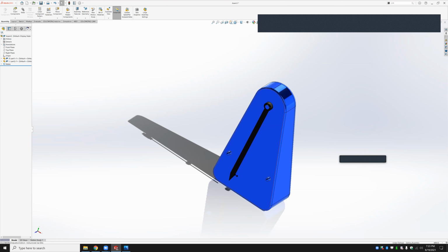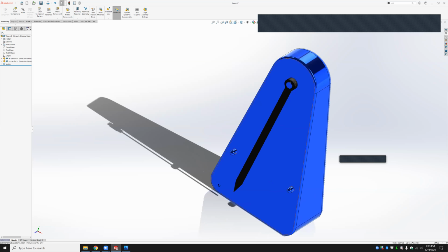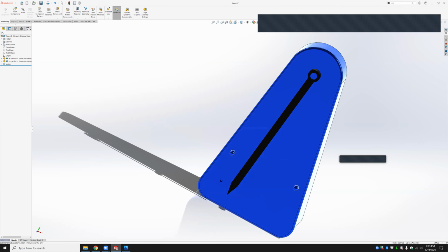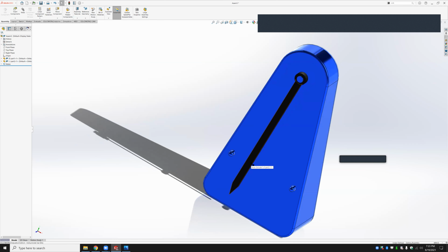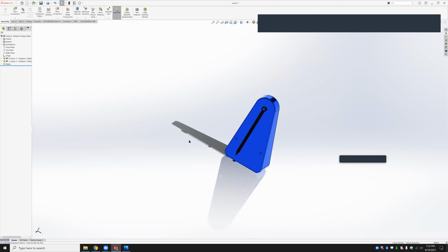Okay. So because I haven't introduced the mate yet, I'll introduce the limit angle mate. It's an advanced mate, and I think it's worthy of the name advanced mate. It's not terribly advanced, but I think it's worthy of the title. How it works is you usually select 2 planar surfaces that are free to move with respect to each other, and you define 2 angles.